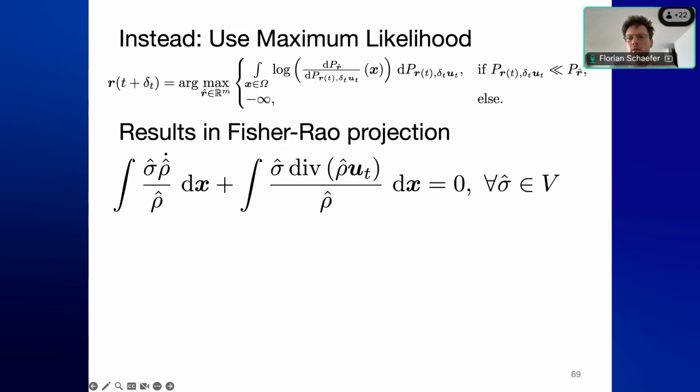I would think so. There are a few things. For the first part, the shock capturing part, my go-to thing would just be to add this to the pressure tensor, like add the sigma to the pressure tensor. And my prediction is that it will help diffuse shock singularities. That would be, without making a research problem out of it, the thing I would try and that I would be optimistic would help.